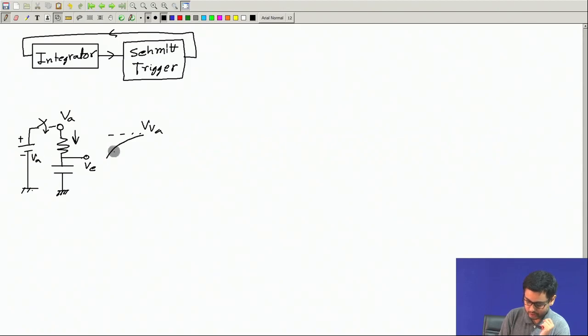Okay. So, this is also like an integrator circuit, precisely not an integrator. Had it been a strict integrator, then for this constant input voltage the output should grow linearly and indefinitely like this, but this will grow exponentially and will saturate.